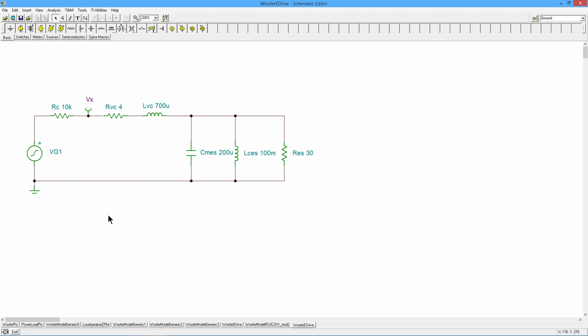And then what you do is you just pick a bunch of frequencies on either side, 2, 3 frequencies below Fs, 2, 3 frequencies above Fs, and that'll be enough to give you data for the shape, right? The shape of that curve. How thick or thin is it, right? What's the Q? Then do a couple of higher ones, like 1 kilohertz, 2 kilohertz, 5 kilohertz, 10 kilohertz. That'll give you all the data that you need for the high end, in other words, this guy over here, or the more fancier version of it.